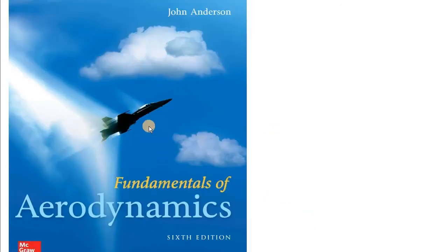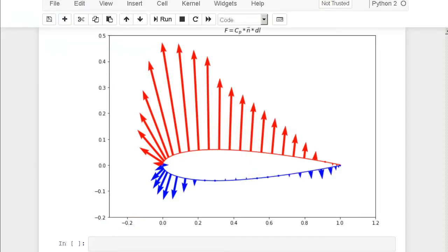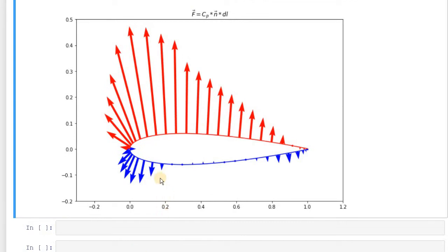Also, we're going to talk about the possible misconception in this subject, but first let's do the basic introduction to this field. Let's assume we have a distributed force acting on each panel element of this airfoil, and let's choose some particular point and compute the moment about this point. For each panel we're going to have the corresponding elementary moment, and then we can sum all those moments and get the total moment for this particular point.